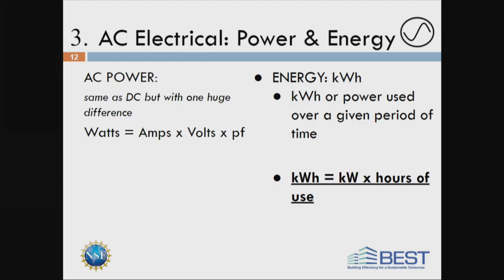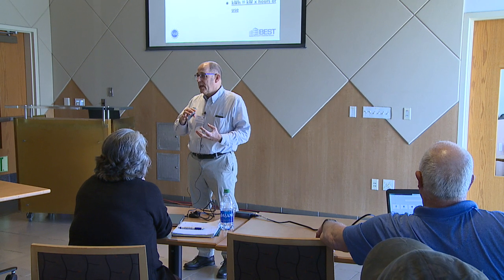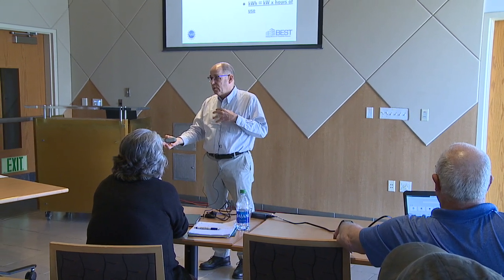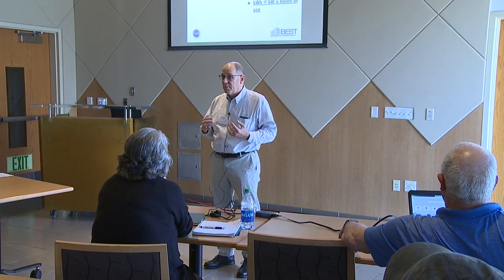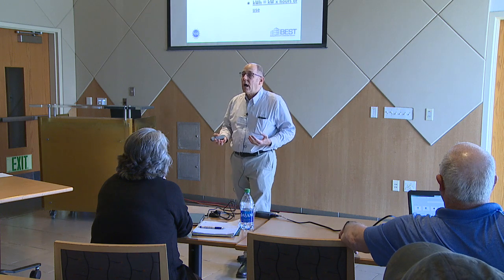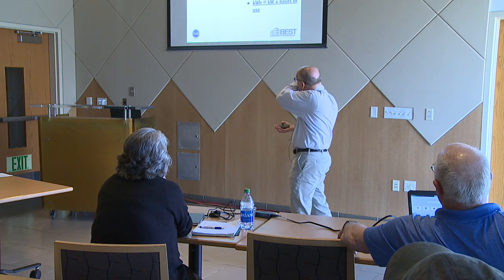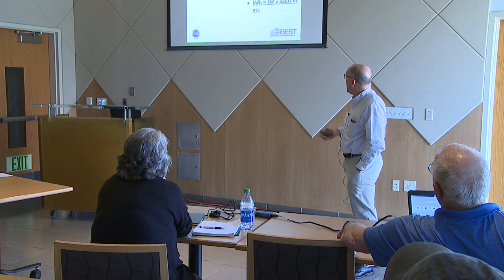The power factor is actually the relationship between the energy that does the work that you want, compared to the total power being used. And the total power includes a little bit of something other than pure resistive loads, inductive or capacitance type of loads. So there's this reactive component to it. Power factor accounts for that.